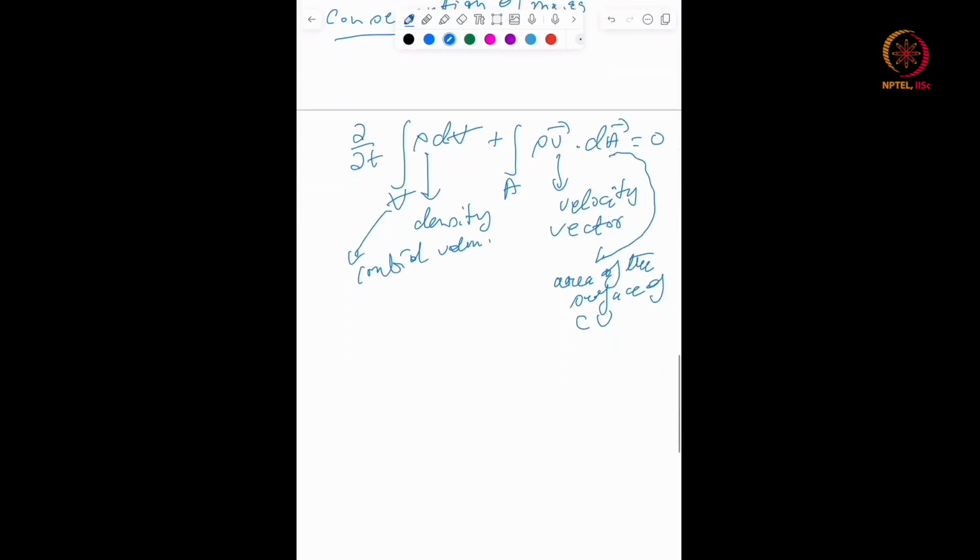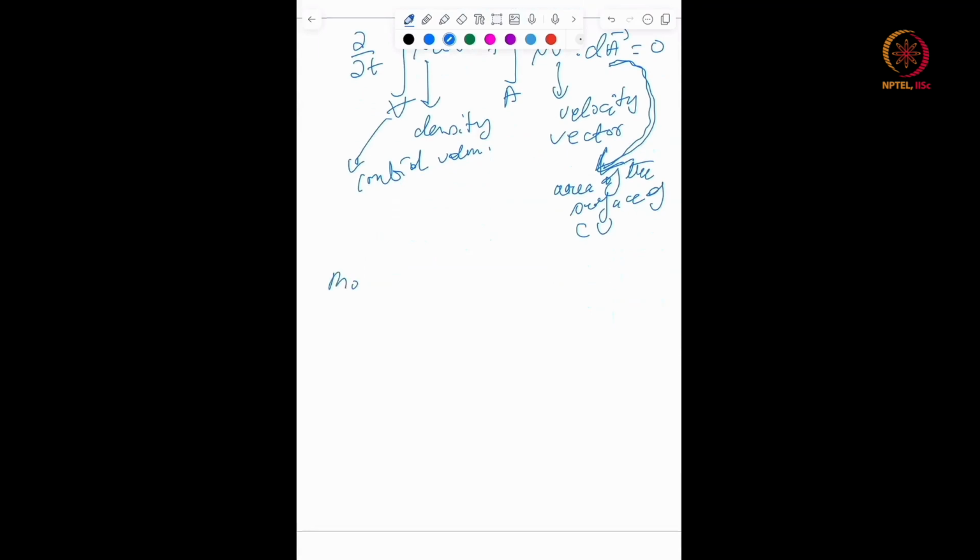So this is all standard. For a non-reacting multi-component flow, you can have similar equations expressing the species. And remember, in combustion dynamics or combustion diagnostics, that is also an important parameter. So this is the mass conservation. Similarly, you have momentum conservation as well. The momentum conservation is basically nothing but Newton's second law.